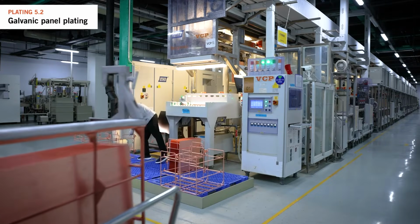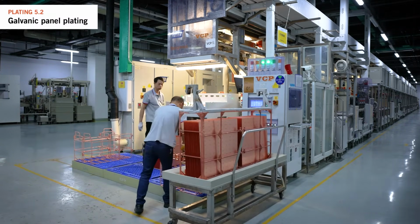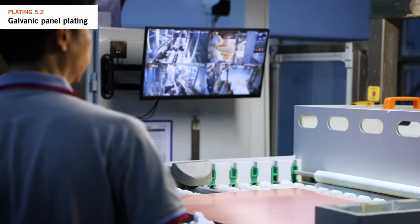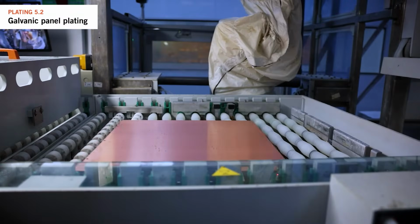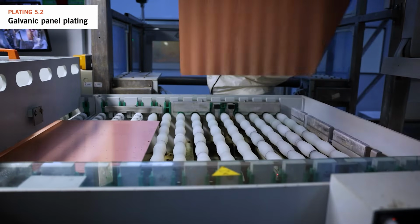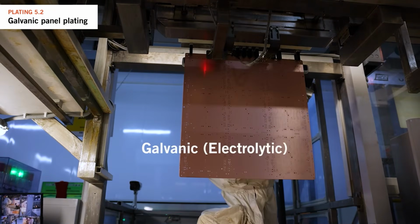The previous process only plates a very thin layer of copper, and this thin deposit isn't sufficient for the next steps, nor is it sufficient for the final working circuit. That's why we need to add a thicker layer of copper to the surface. The panels are processed using the vertical electrolytic plating line to receive the first stage of additional copper.